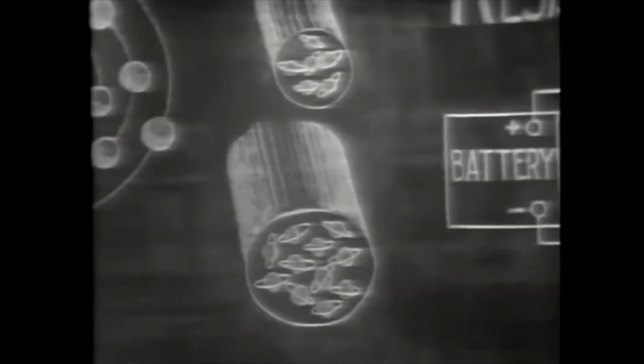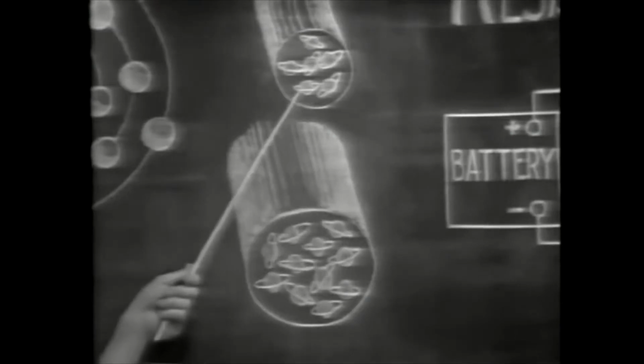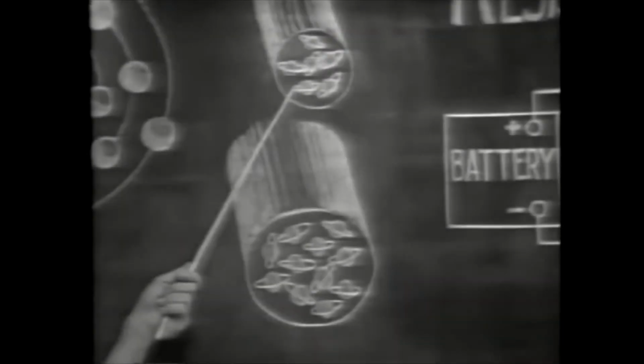This is also easily understood. This, in view of a large and small wire, shows that the large wire contains more atoms. With more atoms, there are more electrons available. And with more electrons available, it will pass current easier than the small wire. Then, as the diameter of the material increases, its resistance decreases.